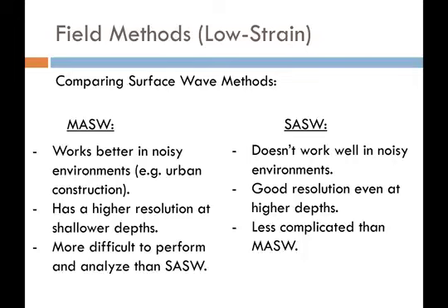Now, SASW testing, on the other hand, does not work very well in noisy environments, but if you have an environment where you can perform reliable readings, you can get really good resolution even at great depths, like tens, potentially even hundreds of meters down, depending on the spacing of your geophones. And it's also a lot less complicated than MASW, in my opinion.